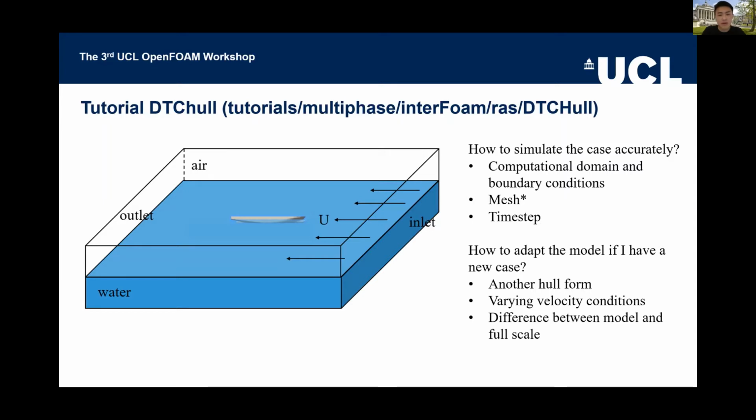Another point here: look at the computational domain I drew. The velocity comes from the inlet to the outlet. One of the things we already learned in seakeeping problems is that in the domain, the ship is not actually a ship inside the domain. It is cut out as empty inside the domain, so it doesn't have any mesh inside the ship. It is cut and modeled as a hole. So imagine we have a hole inside the domain and it's moving forward, and the hole will cause the mesh to distort with it.